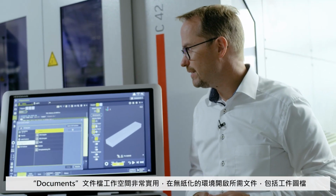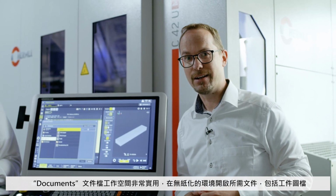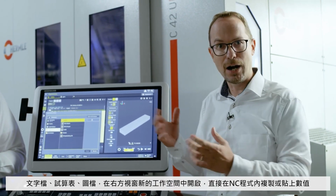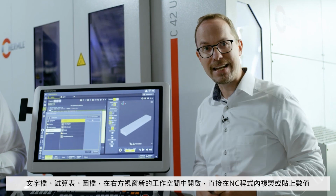One thing that's very useful and exciting is the new workspace called Documents. Its aim is to get you on your way to paperless manufacturing. All necessary documents, such as the workpiece drawing, Word files, Excel files, or image files, perhaps the clamping situation, can be opened in the new Documents workspace, right next to your editor operating mode. Simply copy and paste values directly to the NC program.